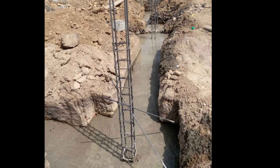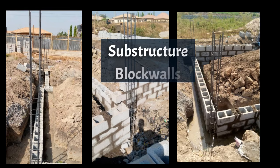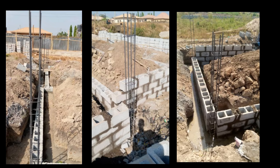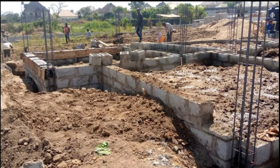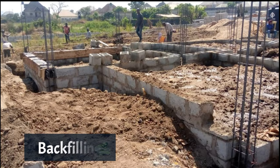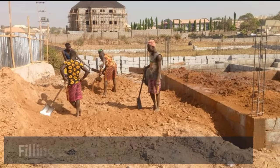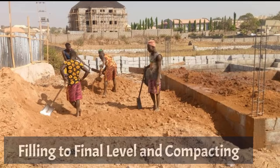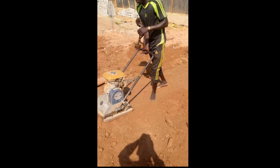Immediately after the concrete in the foundation is completed, the next items of work followed. 1 was the laying of substructure block walls. 2, the casting of the starter columns. 3, backfilling using suitable excavated material. 4, filling to level and compacting. Laterite was delivered to site, manually transferred and spread, then wetted and compacted using a hand-operated roller.